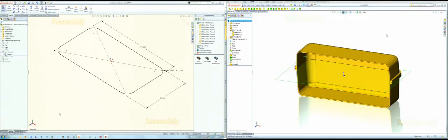We could, but somehow we're going to have to link them to the top of the part. So I'm going to use sketch fillets here, but I'm also going to use a feature fillet here in a second, and I'll show you how both of those are going to translate over to the top of the box. One other thing that's done in here, just so you know, I've renamed a couple of dimensions just to keep them all straight. So there's really a length, a width, and a corner radius, which will come into play in a while. With that, it's just an extrusion,